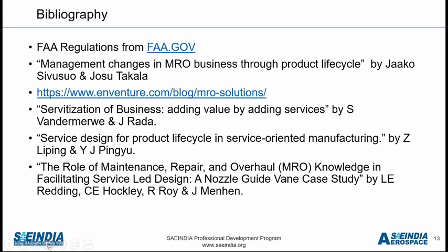In the C check, an aircraft will be completely opened and they will go into each and every nook and corner of the aircraft, look for every component and, as per their maintenance procedure, do the complete maintenance. And then I think D checks, they go for 5 or 6 years in service. But these are not regulated numbers. These are always driven by the OEMs. Okay, great. Thank you. Yeah, thanks.